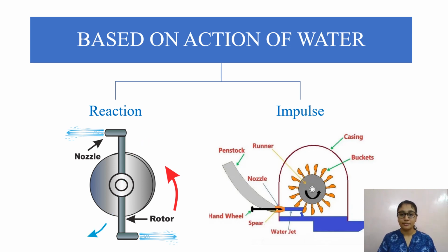Prior to hitting the turbine blades, the water's pressure or potential energy is converted to kinetic energy by a nozzle and focused on the turbine. No pressure change occurs at the turbine blades, and the turbine does not require housing for operation. Newton's second law describes the transfer of energy for impulse turbines. Impulse turbines are often used in very high head applications.